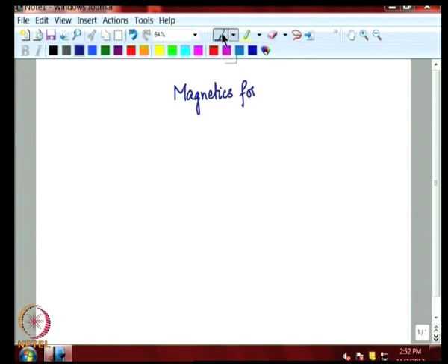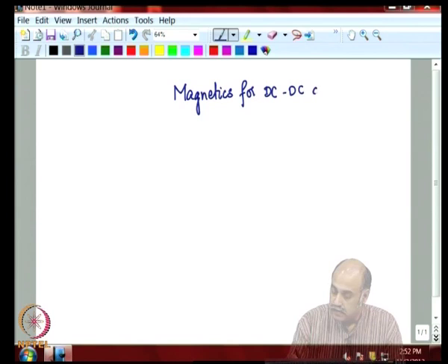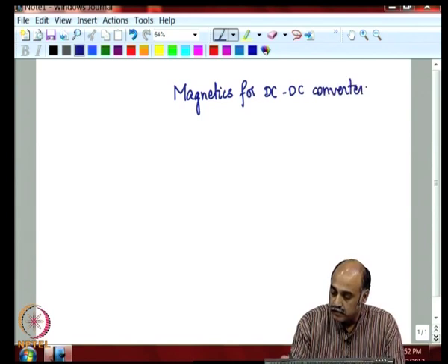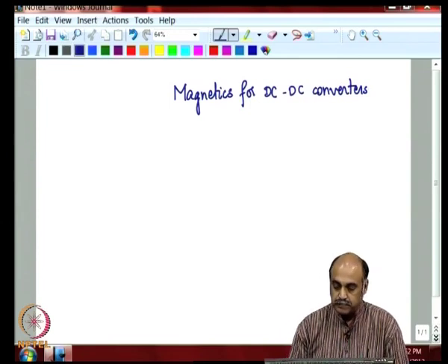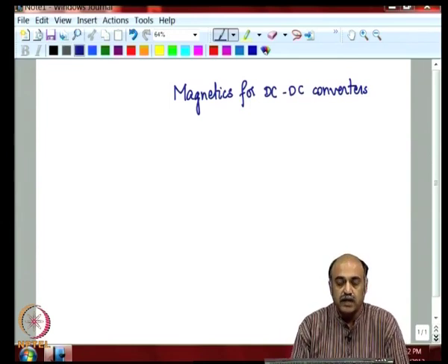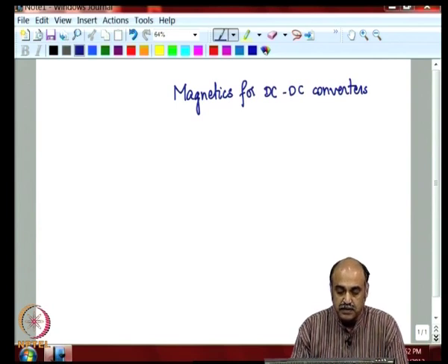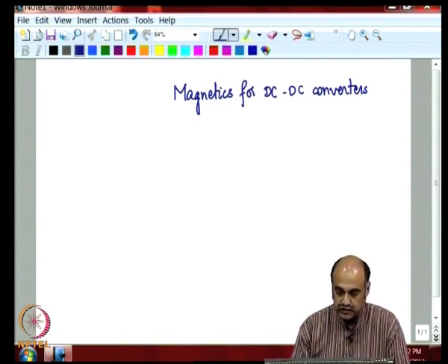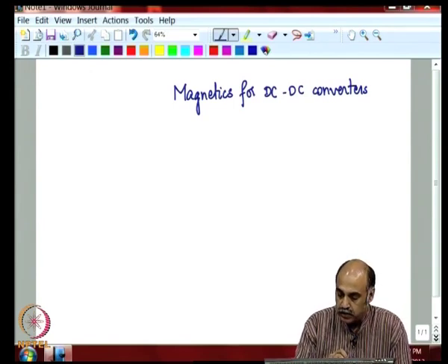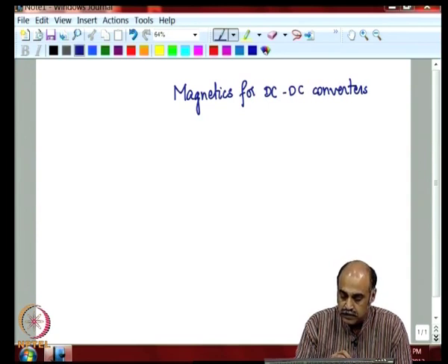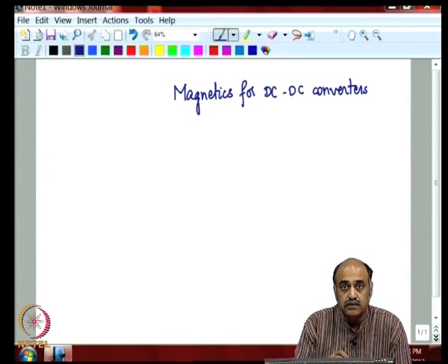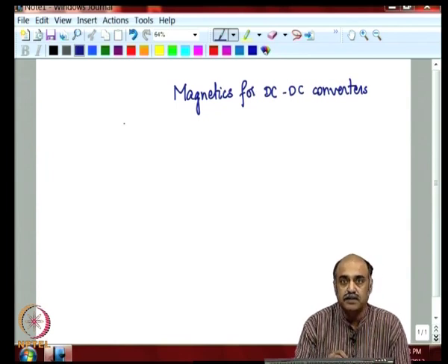However, once a design is performed, the magnetic components, being passive, are very robust. So, nothing happens to them, unlike the power semiconductor switches or the capacitors, both of which may blow once the rating is exceeded. In the magnetic components, the only ratings that can be exceeded are the currents and the saturation levels, which will cause other components to get damaged, not itself.